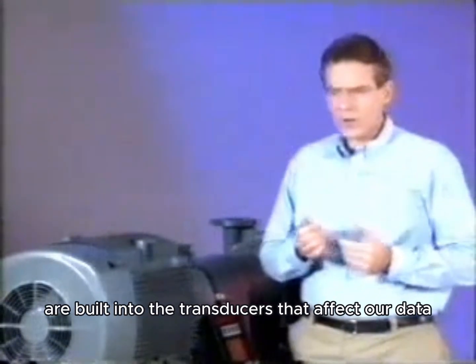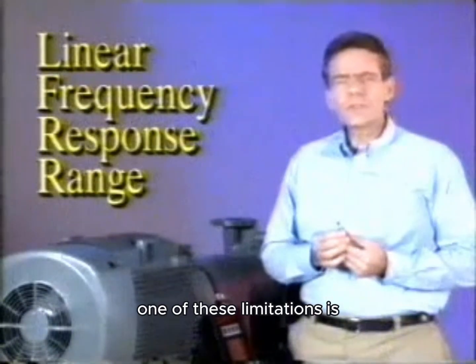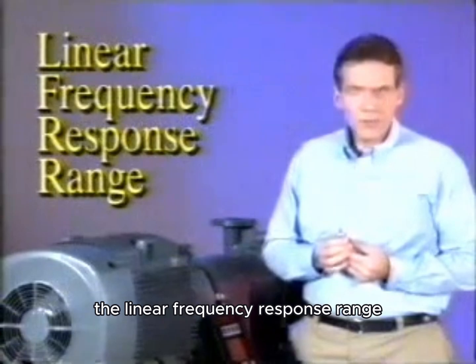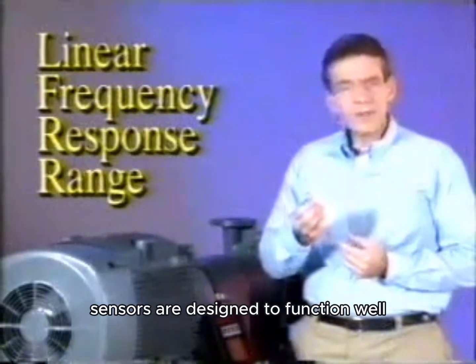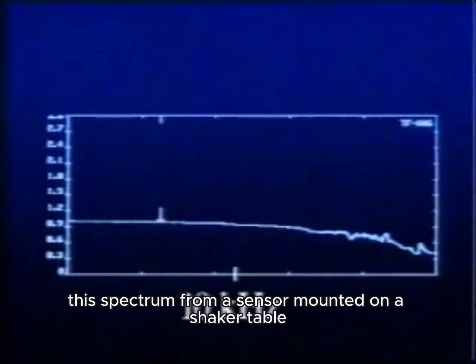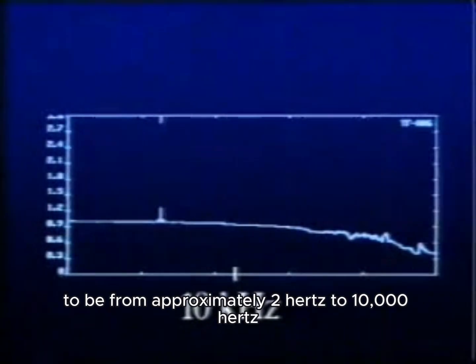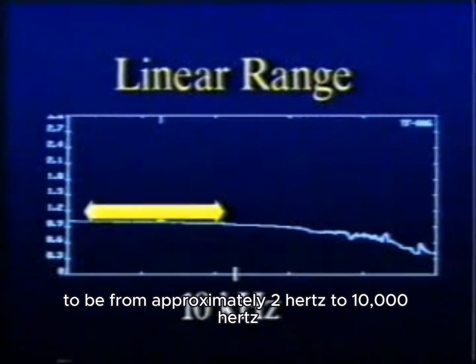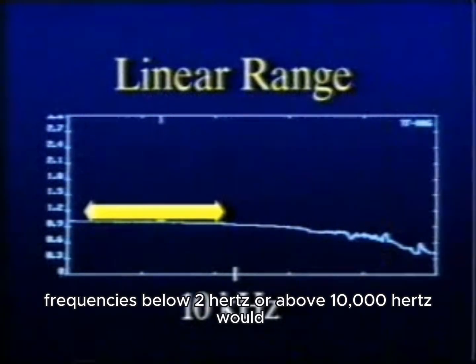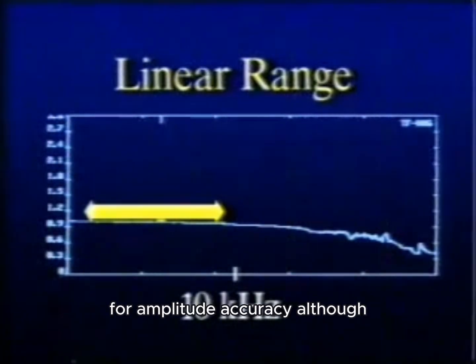Other limitations are built into the transducers that affect our data. One of these limitations is the linear frequency response range. Sensors are designed to function well in certain frequency ranges. This spectrum from a sensor mounted on a shaker table shows its linear or stable frequency range to be from approximately 2 Hertz to 10,000 Hertz. Frequencies below 2 Hertz or above 10,000 Hertz would not be accurate in amplitude. Another sensor must be used that is linear in those ranges for amplitude accuracy.